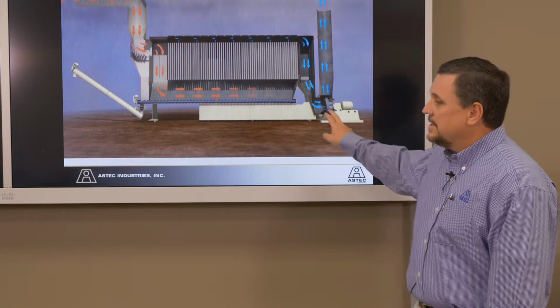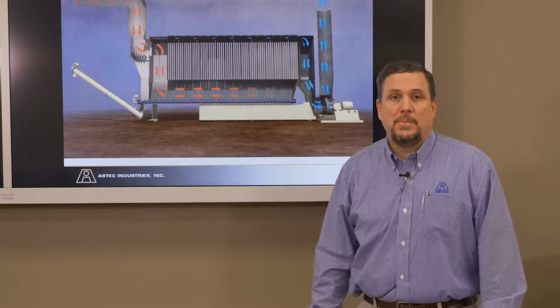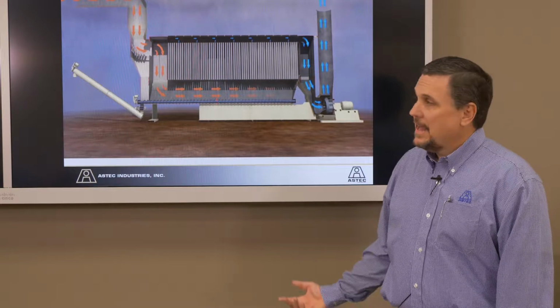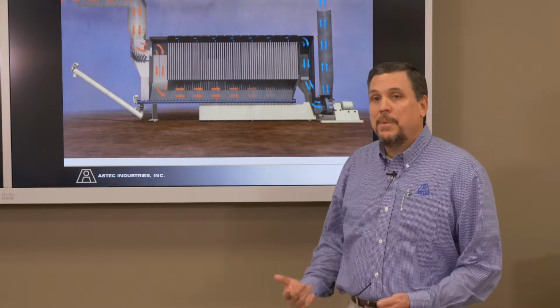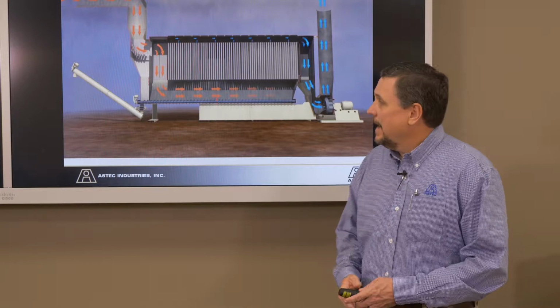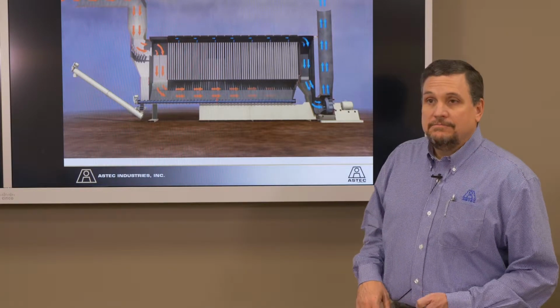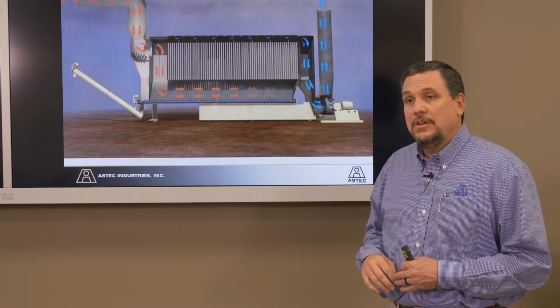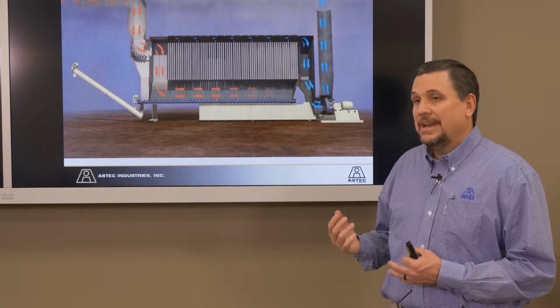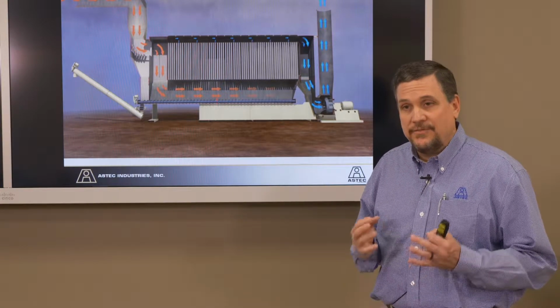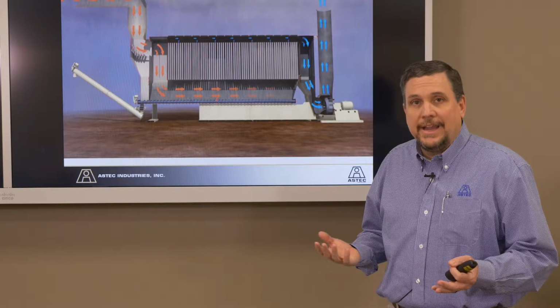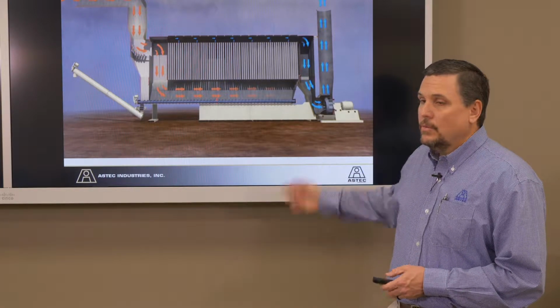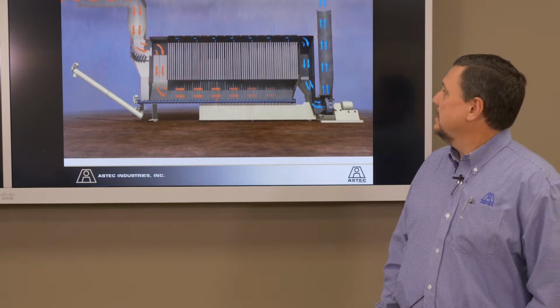One thing in the United States, every state has to go to a particulate test. And that particulate test is basically how many particles are you blowing into the air. Everyone has to meet that requirement. The other thing that you see in some states is you have to do flue gas analysis, and that really is how you tune that burner to be as efficient as it possibly can, and you have regulations you've got to meet on that. But everyone has to make sure they have their baghouse maintained well for the particulate test.